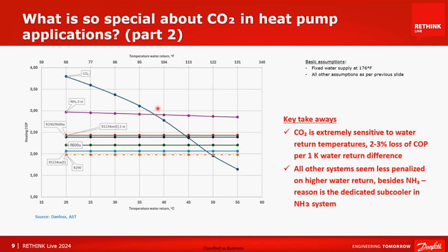because if we have a buffer tank to be heated, let's say, for 8-10 hours in a batch process, then at the beginning of the process we have cold water entering the gas cooler, so low water return temperature, excellent COP. However, at the end of the process, where we have already heated the water tank significantly, the return water is becoming hotter and hotter, and then the COP is not that great.